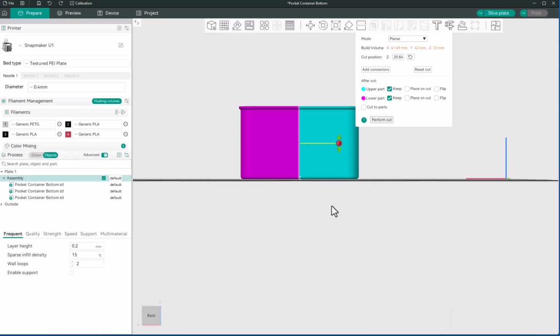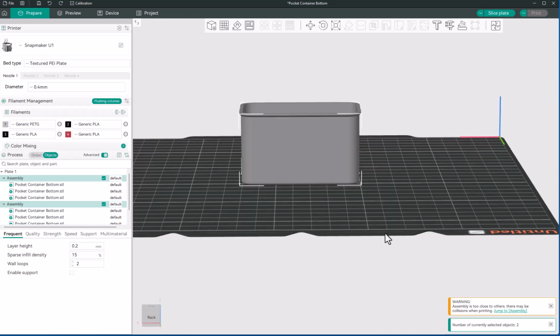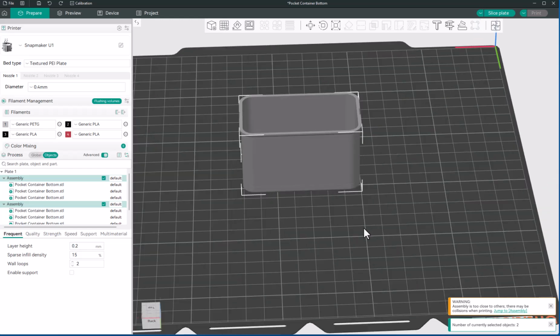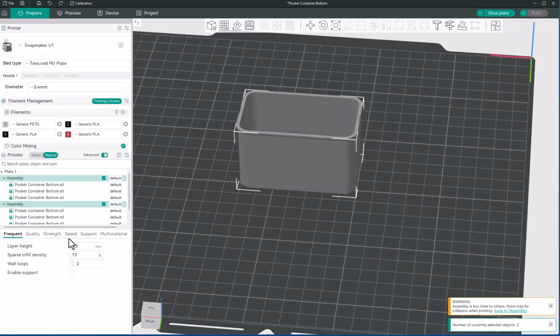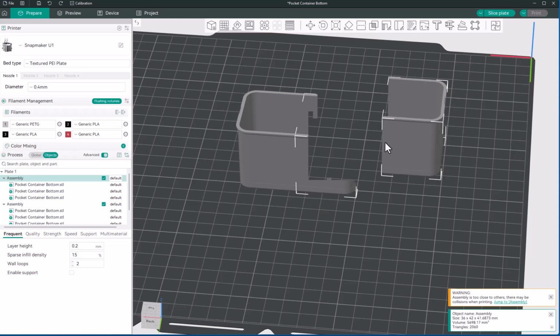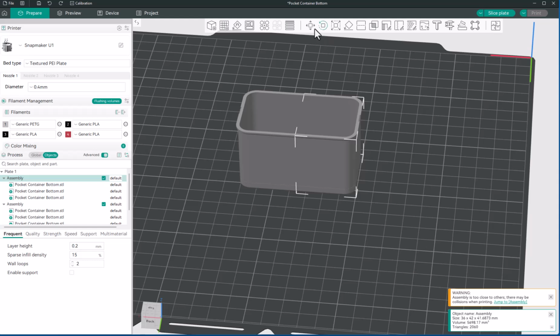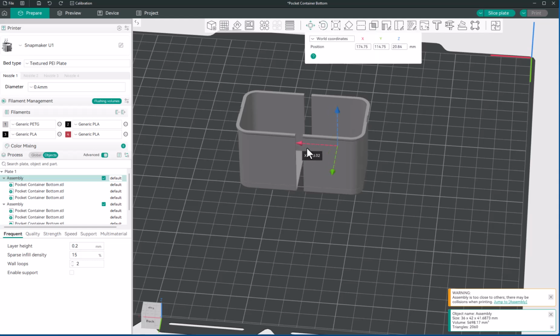Now I want to look at that bottom, because if I select this right side here, and let's see, should be able to select one side or the other. Okay, here's the right side selected. Always when you're moving stuff, if you just grab this like this, it's going to be hard to line up. Okay, so I'm going to hit undo. I always try to hit the move, because the move is going to give you the arrows and how you're going to move this around.